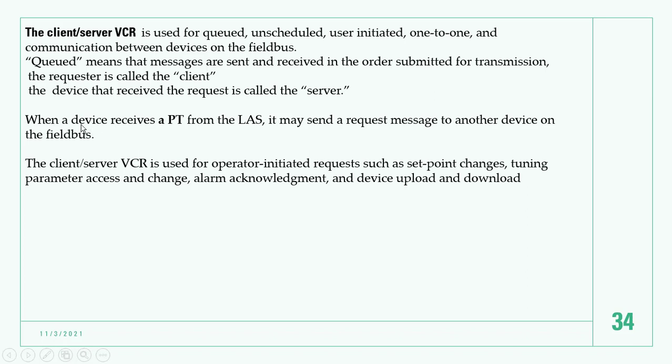Okay, when a device receives a PT, the pass token, from the LAS, it may send a request to another device on the Fieldbus. The client-server VCR is unscheduled, used for operator-initiated requests such as set point change, tuning parameter change, alarm acknowledgement, and device upload and download.